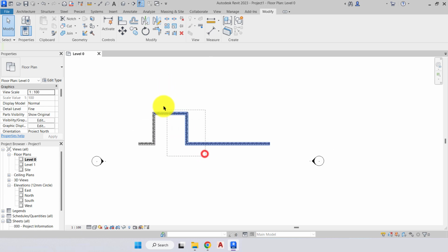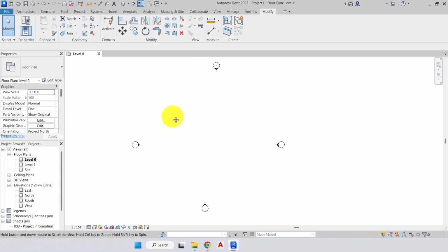What I want you to do is to finally just highlight those walls and delete them so we have a nice clear project to begin with, as in the next video we're going to start to look at developing our building. If you have accidentally deleted these elevation bubbles, close it down and start a fresh project so everything is back to default settings and there will be no issues for when we go to create our project.